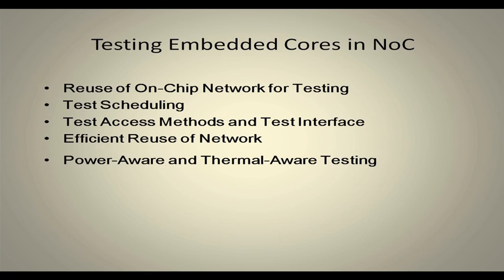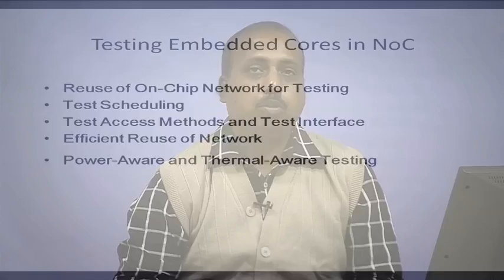Then we have to do test scheduling. Scheduling has to be done just like the SOC testing. So, we say at which time which core is going to be tested. Here also, same thing, we have to talk in terms of the time at which individual cores will be tested. Now, you see that this may lead to some test resource conflict, in the sense that